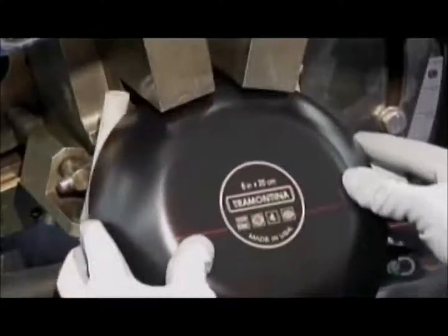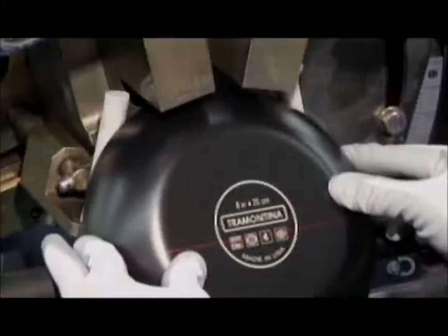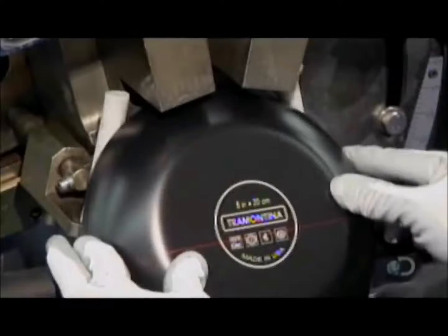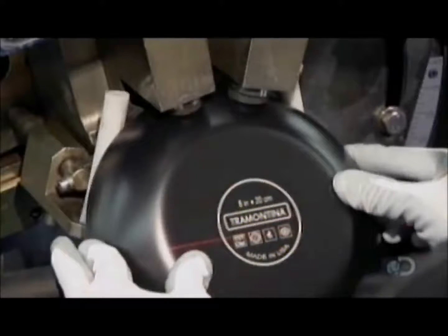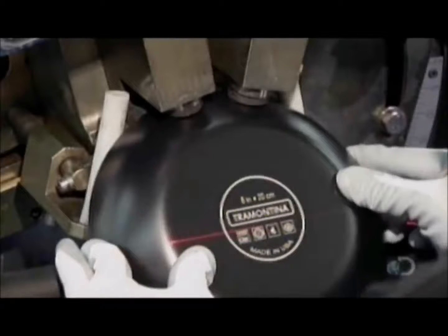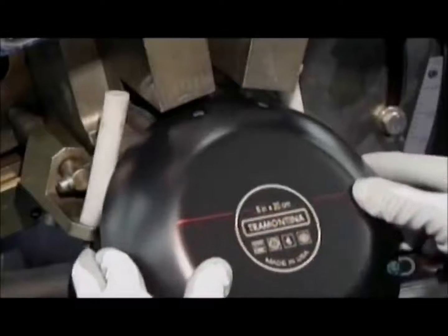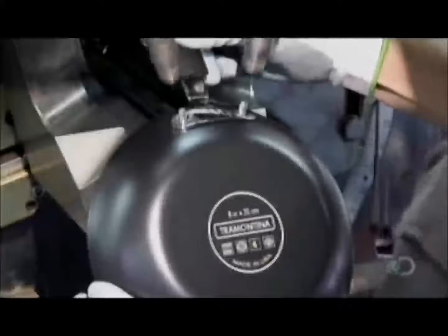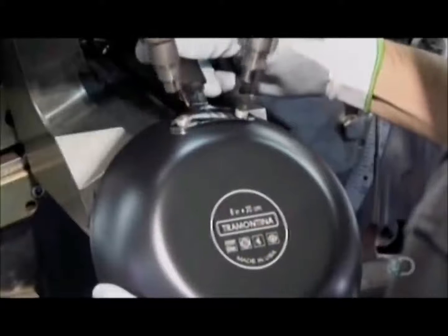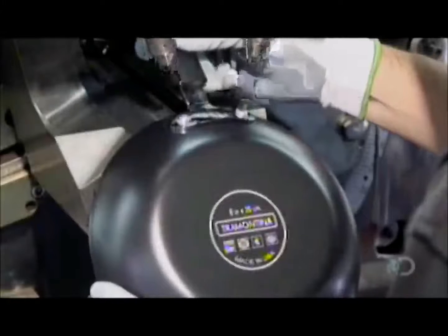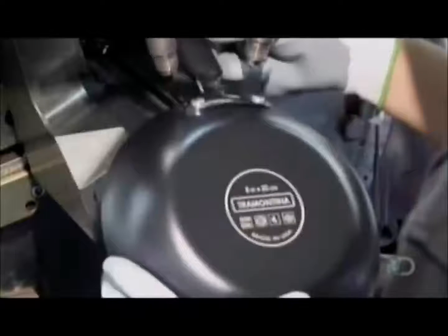At the next station, a laser is aimed, aligning with the bottom letters of the pan, to punch two holes precisely. The punch press makes the holes with force, and it is one type of forging process. The laser ensures the holes are made accurately. Finally, the pin is slid into the hole and slots down through the hole in the handle fitting. Using a ram, the pin is flattened to rivet the handle.